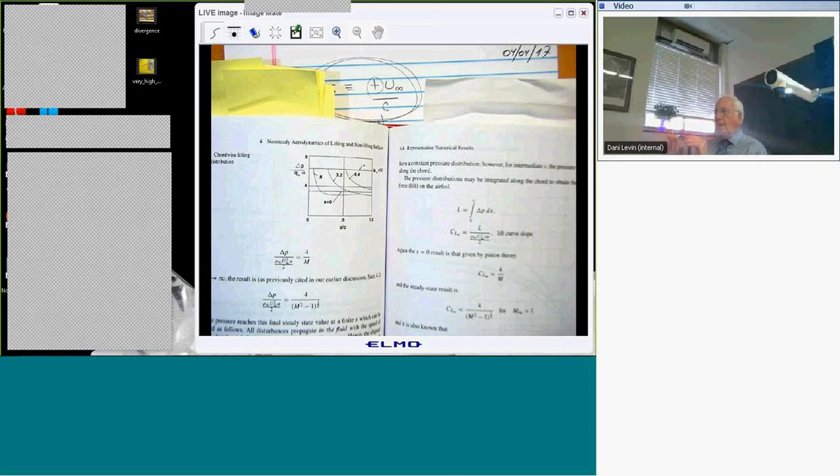Well, remember what's happening. If I'm sitting in the fluid, and the airfoil makes a sudden change, I disturb the fluid. And in the fluid fixed coordinate system, there are perturbation pressures moving at the speed of sound that way and that way, right? But then if I'm sitting on the airfoil, those disturbances look like they're moving this way at U infinity plus the speed of sound.